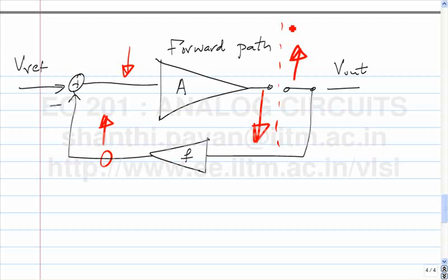So this is the classic test for negative feedback. You break the loop, apply a stimulus at one end, go through the loop and see what comes back, and if it is negative feedback, then the output of the loop will be in the opposite direction of the excitation you put in.